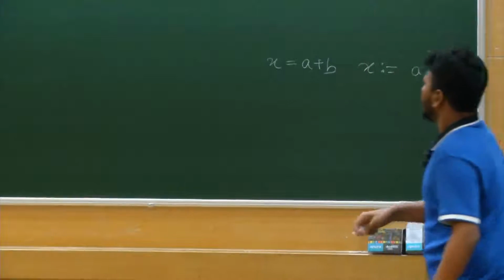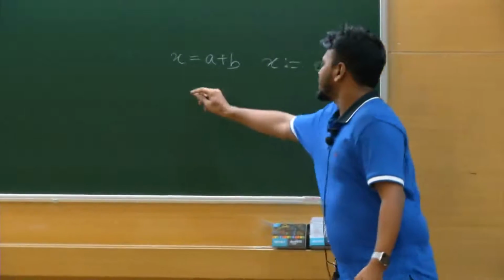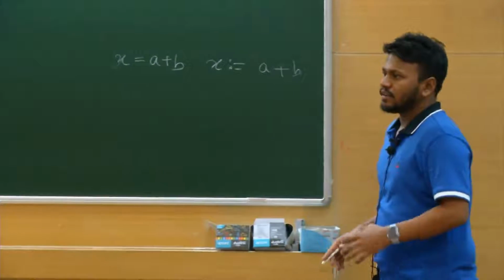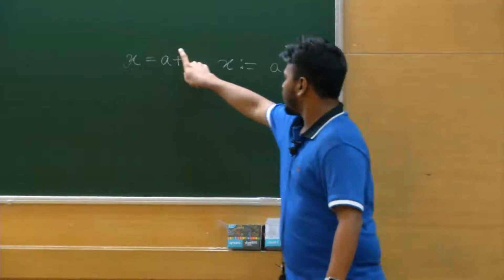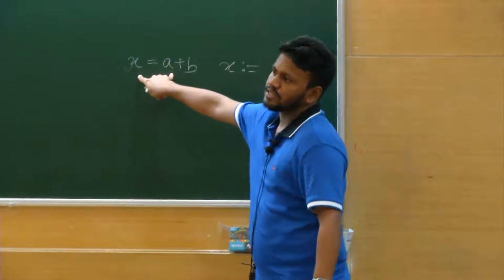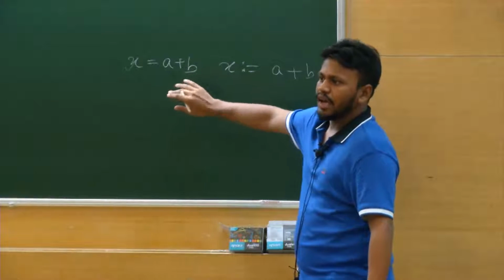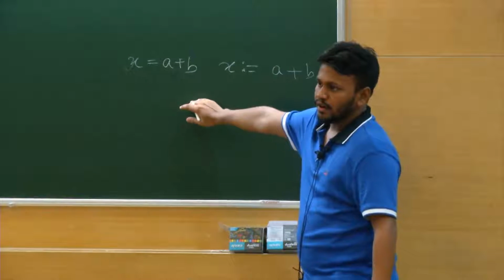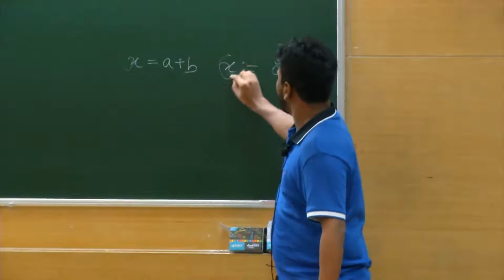So now there are two different ways in which we can write an equation. Modelica generally prefers this style of writing, and I'll explain why. When you write an equation in this style, I can have any of the variables as unknown, with the other two known, and the equation can still be solved. But when I write the other style, I must have A and B known to compute C.